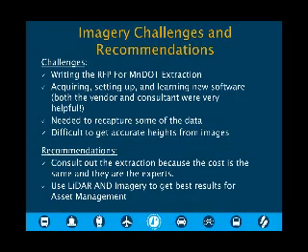But it's important to have QA/QC, and obviously you're going to be using the data, so you'll see if there's any issues with it. Another challenge was it was difficult getting accurate height data from the imagery because we were measuring from the top edge of the pavement, and then we'd move over and there'd be aggregate base, and sometimes there were washouts, so you couldn't really tell off of an image where that point should be. And sometimes it was hard to tell exactly where it was in the image.